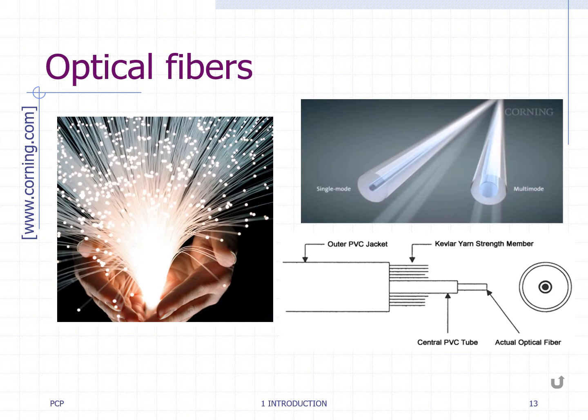Optical fibers are flexible, transparent fibers made of silica, which are used to transmit light in fiber optic communications at higher data transfer rates than electrical cables. Single-mode fibers are designed to carry light energy on one path over long distances with a core as small as 8 microns in diameter. Multi-mode fibers have a larger core measuring up to 62 microns in diameter and are built for light signals that must travel many different paths simultaneously, usually over shorter distances.